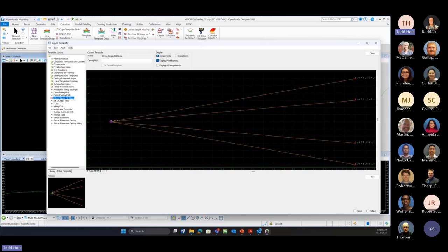But what if we now want to make a fill slope end condition, but we have a fixed 10% slope shoulder that's going to tie into a ditch. That's going to be our second part. So we have a recovery zone that we want to build that's going to come out from our shoulder. We're going to build that into our end condition. We're going to go a certain berm, and then we have a ditch. We're going to build that out in there.